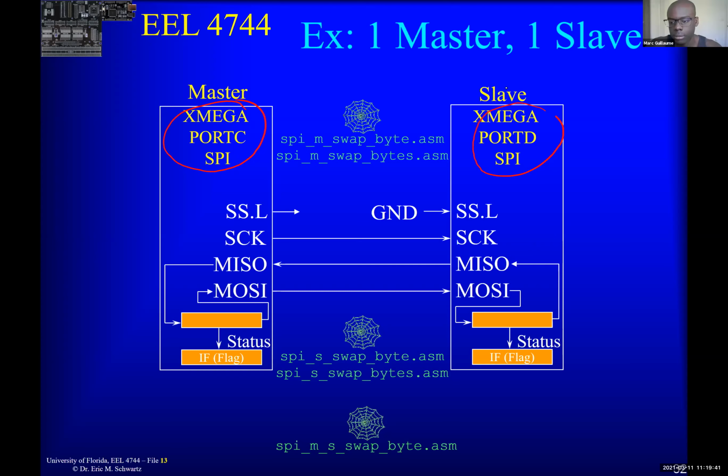Whatever. Okay. So anyway, we're going to go through these a little bit later, and so we'll set the master slave to be an output. With some peripherals, you can make the slave select always true. For the XMEGA itself, you can make the slave select always true if there's only one slave. But the IMU that we're using, you can't actually do that because you need the slave select to give some kind of synchronization signal at the right time. But in any case, that's what we're going to do, and I'm going to do five different examples with this.